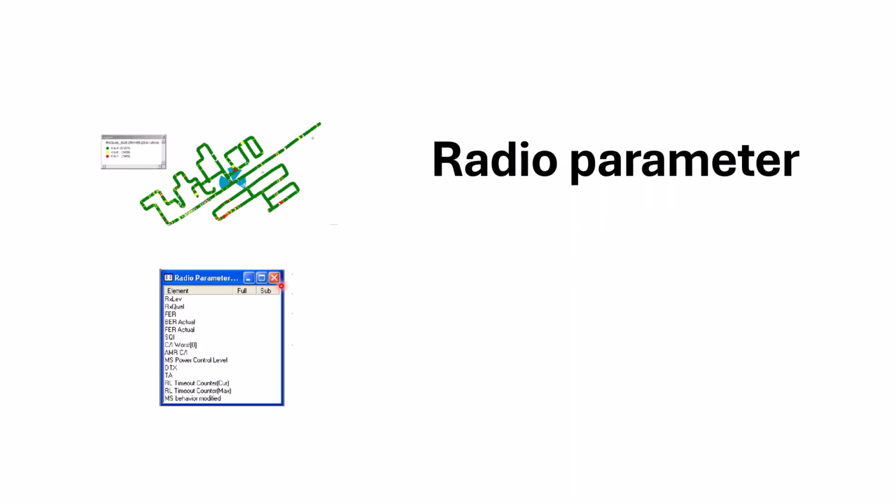RX quality. Definition: average receive signal quality measurement on the time slot based on bit error rate. The threshold is RX 0, bit error rate less than 0.2 is excellent.